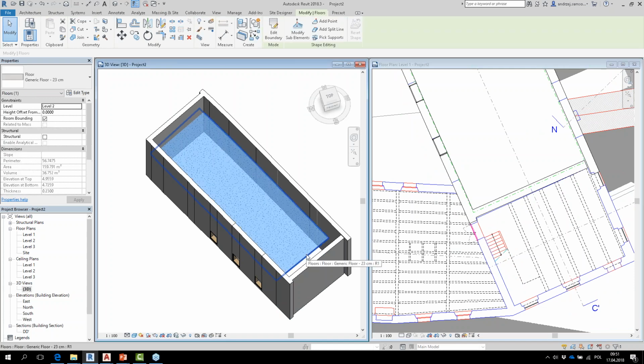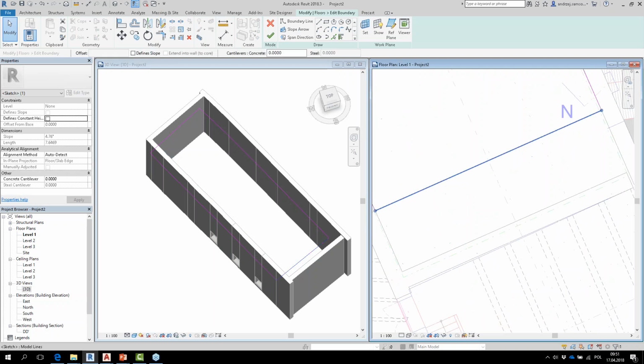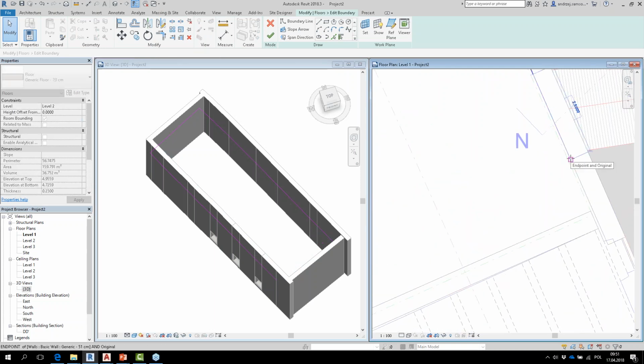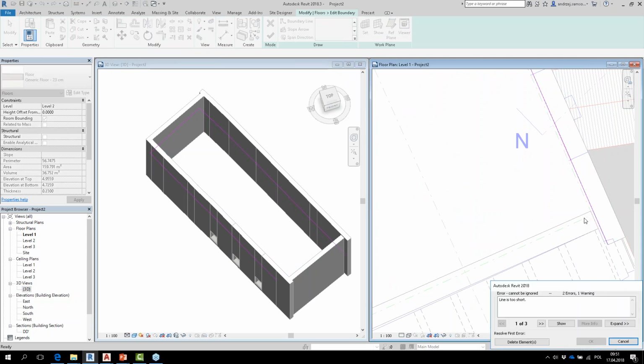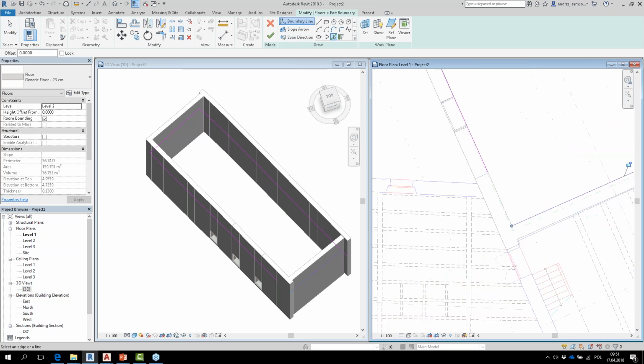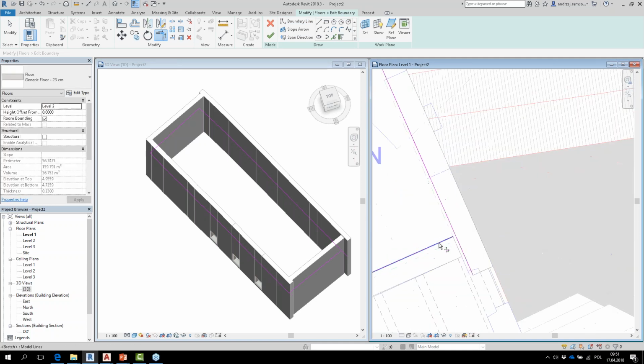Look, I'm gonna click now my floor, edit boundary. Okay, I will delete this because I will have to prolong and take it up to here. Select line, select delete element, and then select this, select this. Here I have some tools like trim. So I'm trimming.